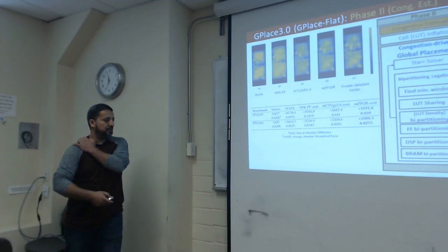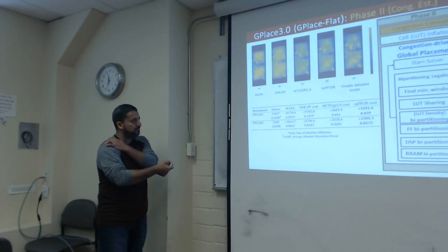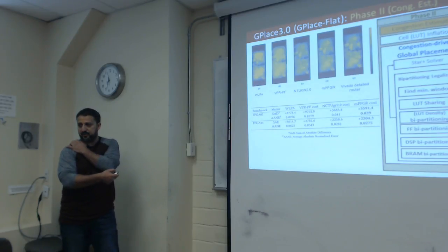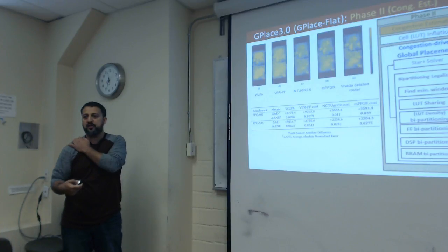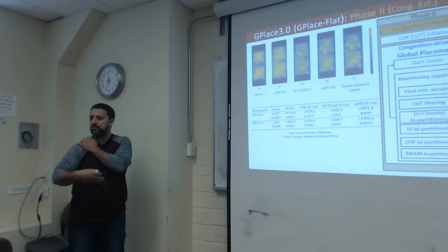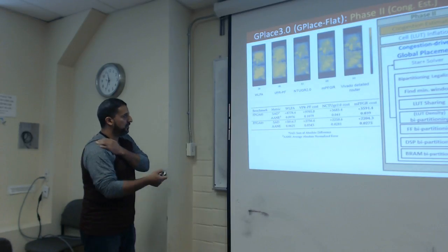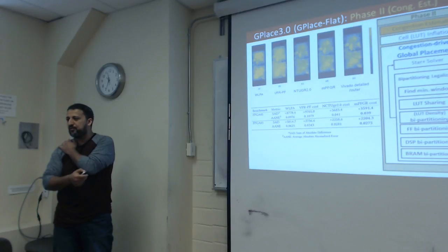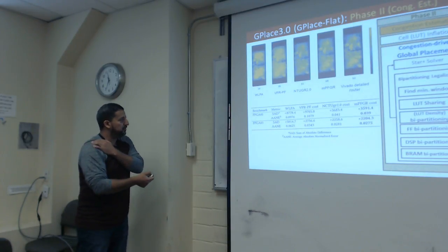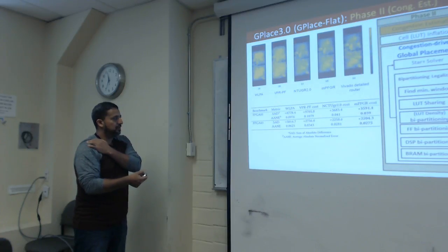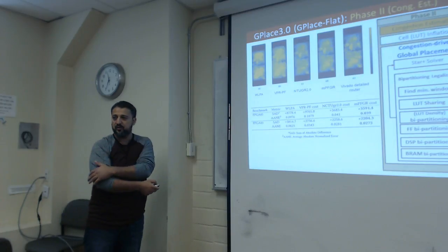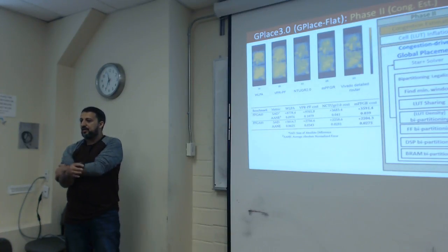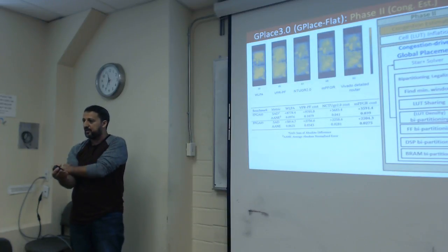We introduce a novel modification of the ASIC global router. We perform Pathfinder, but we use the same cost function that is used for the ASIC global router, after modifying some of the cost functions. And we end up with this: the wirelength per area. This is the cost function used in PBR, which focuses only on wire length cost. This is the cost function used for the ASIC router. This is the modified cost function for a global router. And this is the detailed router heat map, after doing the detailed router and extracting the congestion using TCL script.